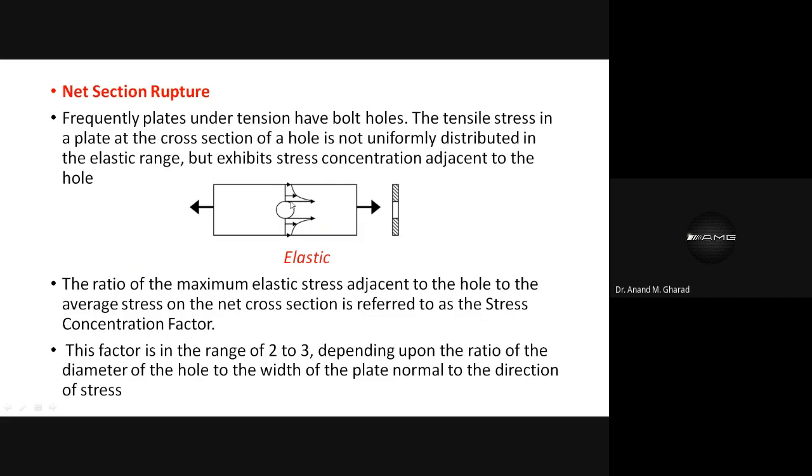Now, over here, as you can see, around this periphery, the stresses are more. They are concentrated in, and the intensity is quite more. And at the plate end, you will see the non-linear variation of this stress. And at this point, or at this point, at the edge of the plate, the stress concentration reduces. Okay, so it is non-uniform. Okay, and what you observe is in the elastic range.